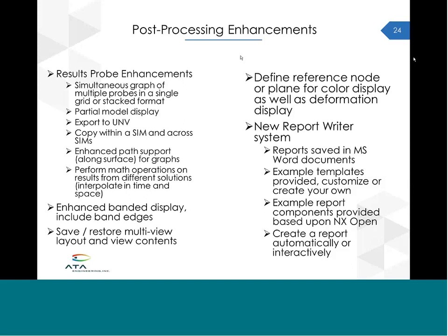One new feature that I find quite helpful is the ability to copy within a sim or across different sim files. There's also enhanced support for plotting result probes along a user-defined path, as opposed to forcing your result probe to follow a geometry edge or element edges. You can now define your own path. And result probes are now also available to math operations, so you can do various linear combinations or interpolate in time and space using result probe results.